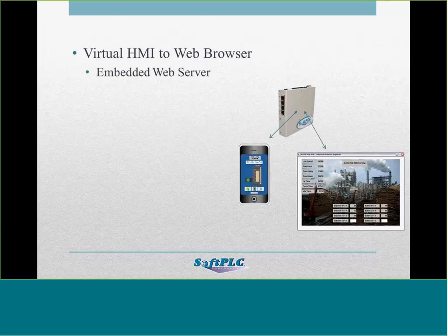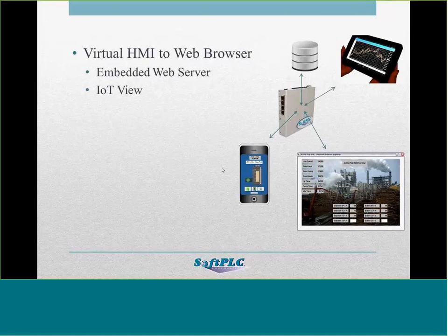So we have two ways of doing that. One is there's an embedded web server option for Soft PLC. We actually were the first controller to support a web server. And with that web server, you can build pages. You can use any development environment and build pages that are bidirectional to read and write to the data table through any web browser. Now, we also have the option for IoTView.